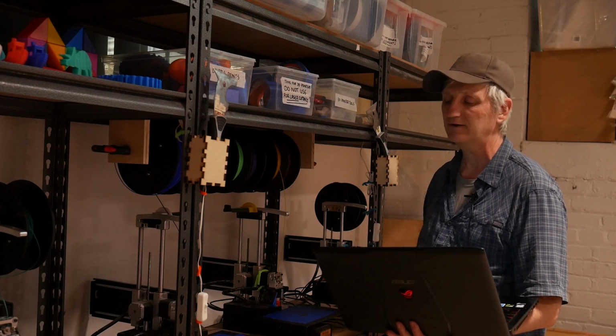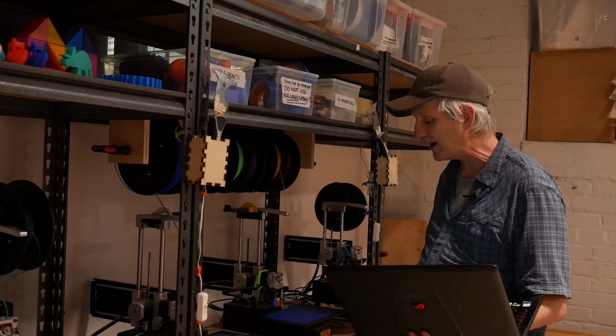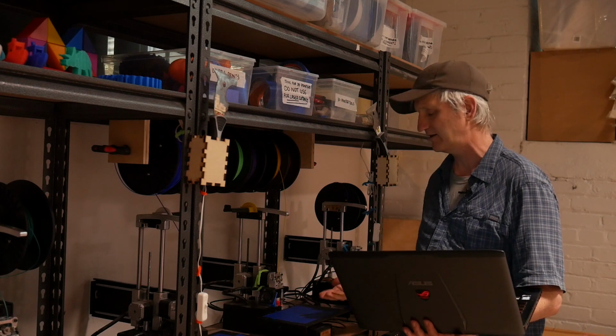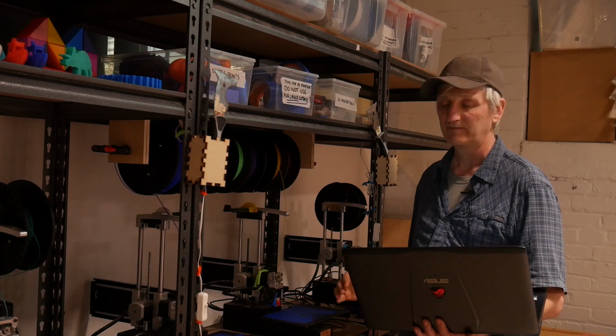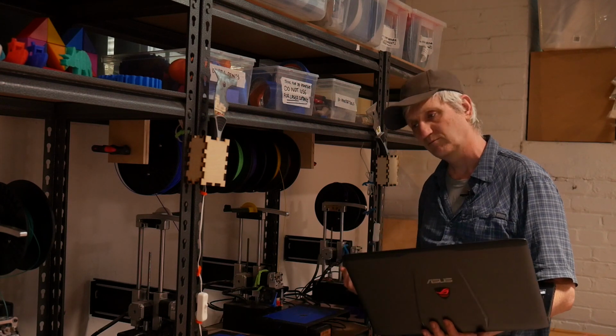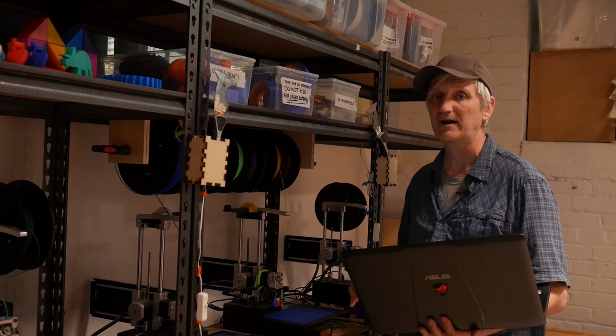The other thing I'll point out is that I'm not just printing my model, I'm also printing it on top of what we call a raft, which is an adhesion technique. So a raft basically does some wide crisscrosses before it begins printing your actual model. And it does this to basically create kind of a semi-permeable layer between your model and the bed. It'll help it stick, but then later on, it'll also be helpful when we pry our model off this thing. This is going to be about, if you remember, about 80 millimeters wide. So it's going to be fairly wide on the bottom there, and it's going to really stick. So without that raft, we'd have a heck of a time trying to get it removed from the machine.